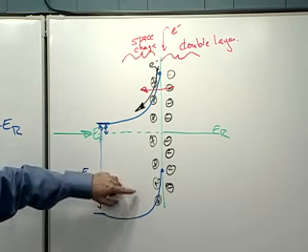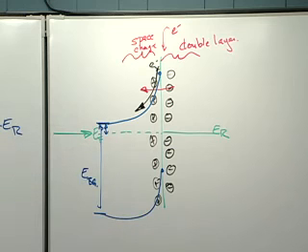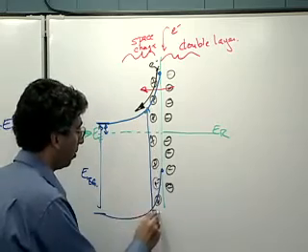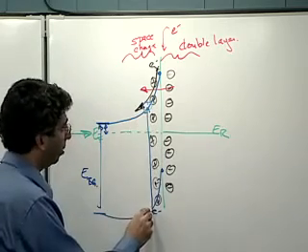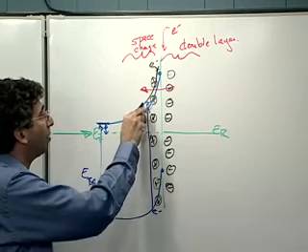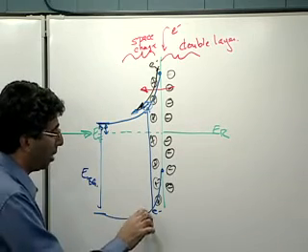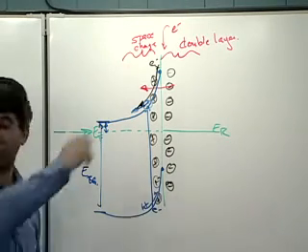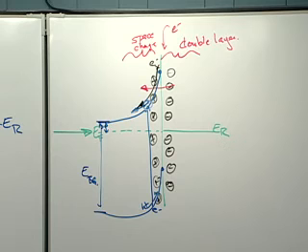Okay. If I now irradiate the surface with energy equal to or greater than the band gap transition, I will promote an electron from down here to up here, leaving a hole down here. And of course, an electron up here. If there's no band bending when that happens, then I just get rapid recombination. But if there is band bending, the electron feels the effect of the field, and it moves into the bulk of the semiconductor, and the hole also feels the effect of the field, as long as I do this near the surface where the band bending is, and it moves up to the surface. And when it gets to the surface, it can oxidize something. So an N-type semiconductor is a photoanode. It oxidizes things in the light.